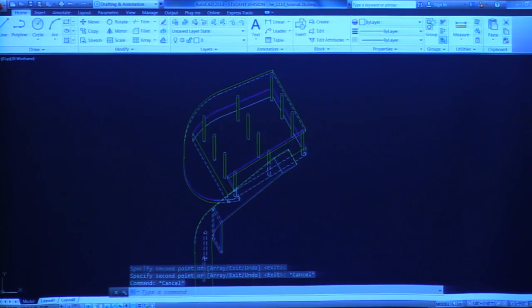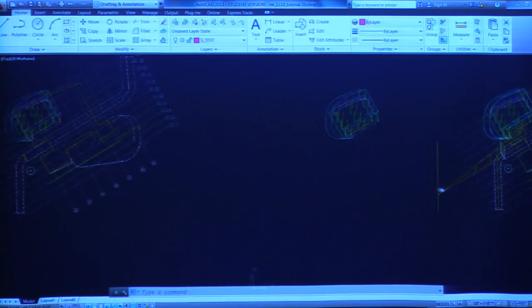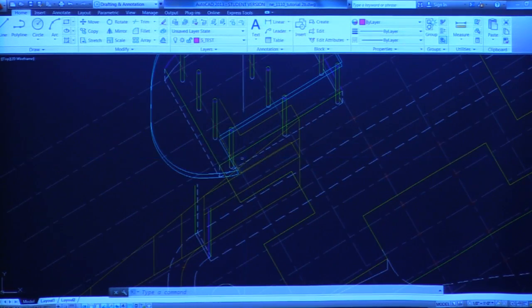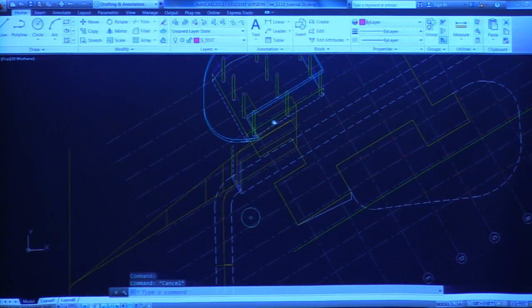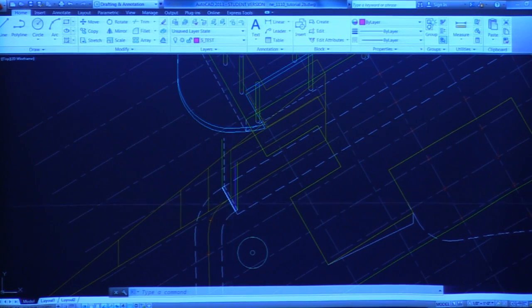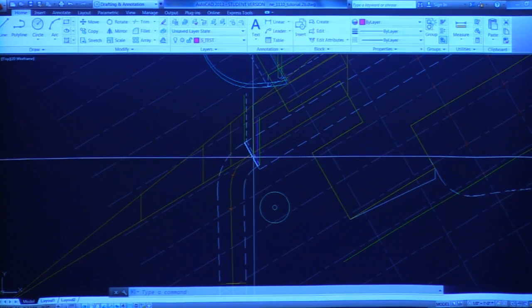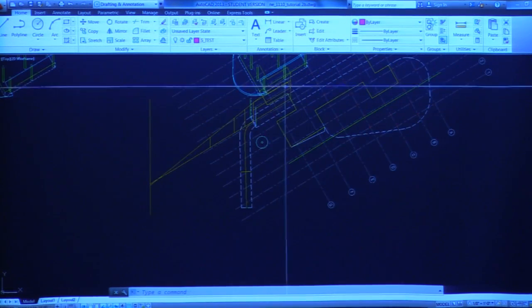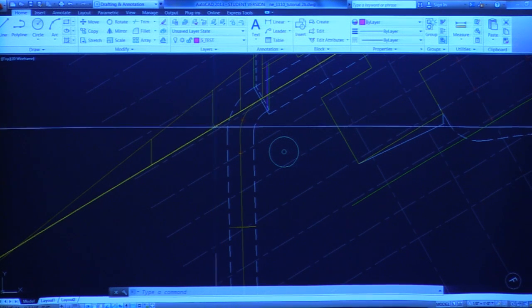I'll show you quickly how I constructed the ramp, at least in a sequence of steps. Basically using the slab heights, I traced around lines to get up to the second story where I know the ramp lands, and then I also used a kind of baseline height. So in this instance, looking at the first floor slab, measuring up to different points on the ramp, and then treating the ramp as a straight line, I took those other points, so I got a length.